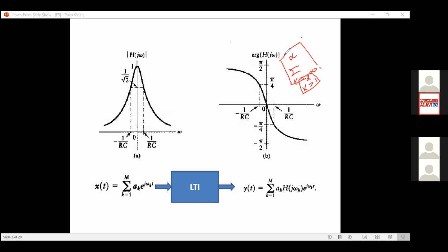For this reason, for general purpose, here it is written, as a very intuitive explanation, and we will go into more detail when we deal with our system: if we can express our x(t) or x[n] as a sum of exponential functions, then you can use the superposition theorem to find the output. For example, for k equal to 1 to m, how many signals are there in x(t)? That means m numbers of exponential terms are there in your input, are they not? Yes, sir. So you are splitting your input like in the convolution sum, where we split our input into many components, say x1(t) plus x2(t) plus x3(t), up to this sum.